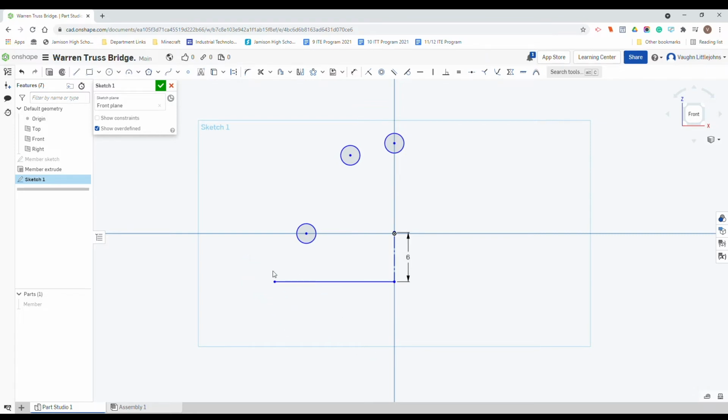So once there, we can now just draw the rest of it. So line tool, we want to go vertically, and this is going to be 15 as well, so click and then just type in 15, and then we are going to put a center line in, so we've got our height.